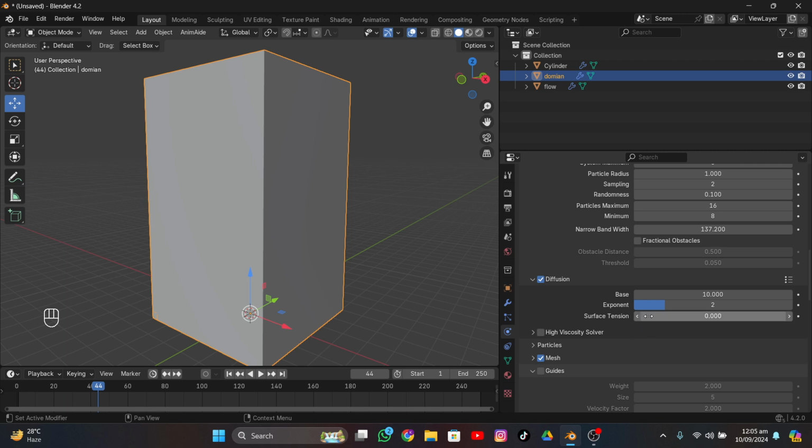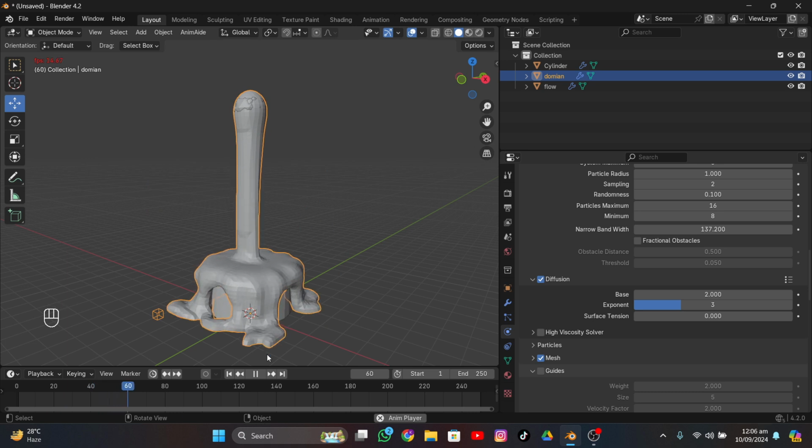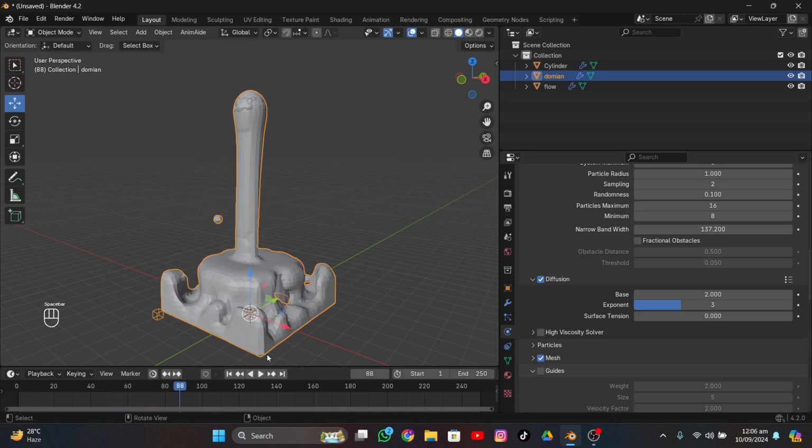We're not going to talk about it right now, but if you look at this, it says that a high surface tension of liquid will result in greater hydrophobic behavior. So for making water stuff, you can just increase this value. The best thing here is that we have presets, so you can choose from those presets. For example, if I go for oil, maybe honey, and as you can see, now this is set to 3. If I replay it, it's going to act like honey, but I think I need more sample resolution to make it more like honey. But you got it.